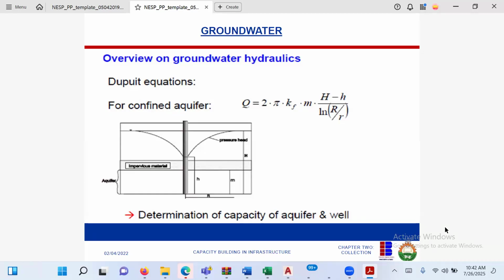So most times, if you want to get a sustainable water that will last for a long time, then you need to look for that river in quotes. You need to look for the river in the ground, which is simply, you need to look for the confined aquifer. Okay, and that's why sometimes you need to drill, you need to overcome some level of overburden. Maybe sometimes also overcome some confining strata before you now approach the real aquifer, which most of the time is more sustainable, though you will require a lot of energy to pump them out.